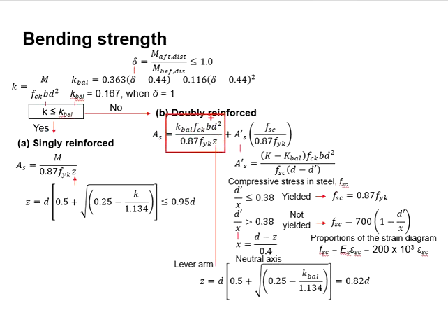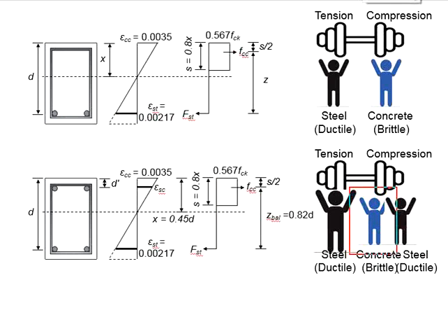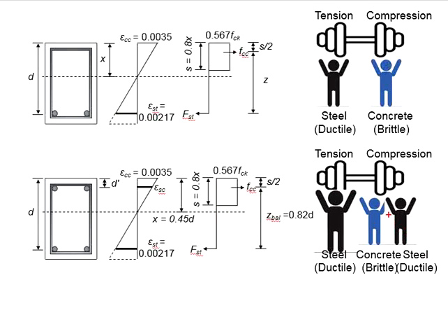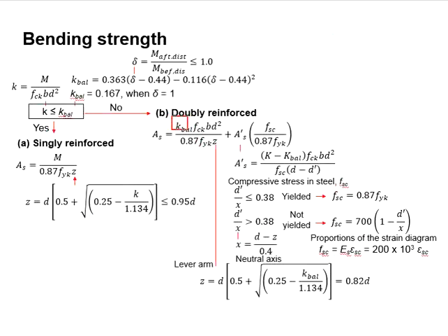And this part here represents the limits of the singly reinforced member. To make it simple, this part represents the largest strength that can be given by this person here. As for the compression steel bar, it will lead to additional compressive strength so that the collective of both is stronger than the tensile steel here. And then when it comes to the K balance and the z, everything will have to work on the basis of 0.45d.